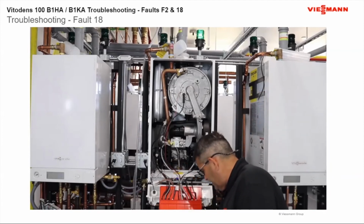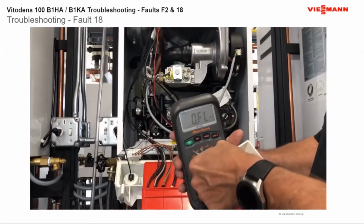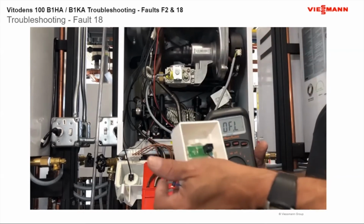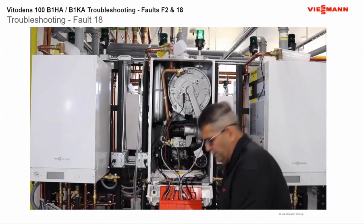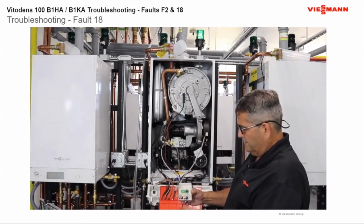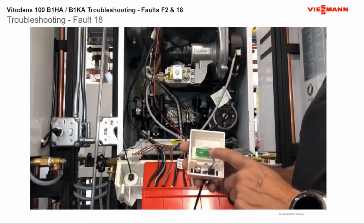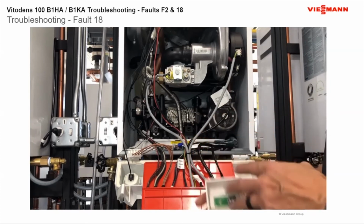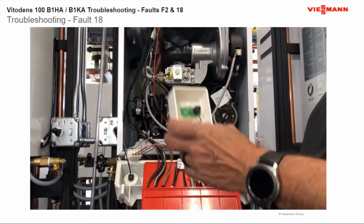But this time we're going to take our meter from ohms and put it on audible, so we can hear to make sure that we're making a complete circuit through our wires. If that checks out well, and we know that that could be the problem, sometimes people cut the wires, we'll do another check with an ohms reading on our outdoor sensor itself. Once we do that, we're going to replace the sensor with a new sensor, if that's the problem.